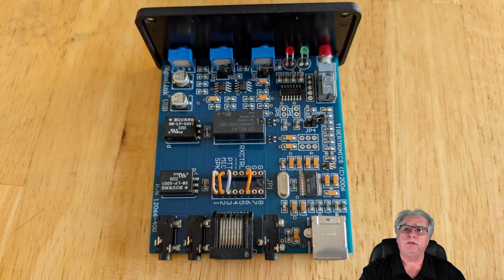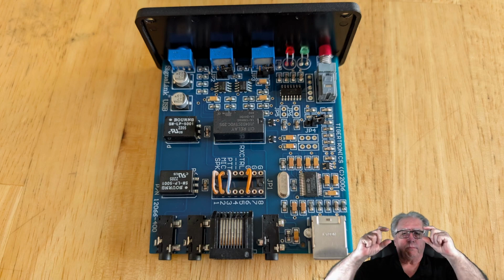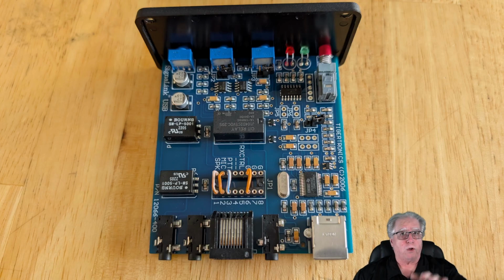And once you do these jumpers, you're going to wire up the cable, that RJ45, to attach to your radio. Nice part about Signal Link is you can purchase a cable from Signal Link that will work with your radio. You can even purchase little block adapters that are just little boards that you push down, and it does all the jumpers for your radio.